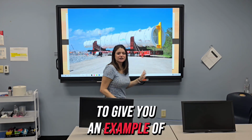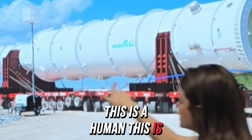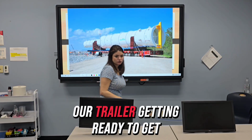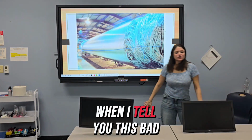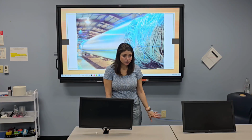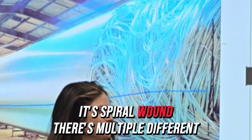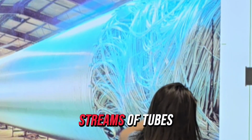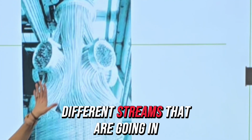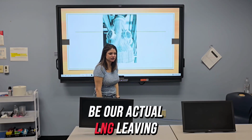To give you an example of how big this thing is, this is a human. This is our main cryogenic heat exchanger on our trailer getting ready to get installed. When I tell you this bad boy is a tube cluster, it is a tube cluster. It's spiral wound. There's multiple different streams of tubes. So you can see here all the different streams that are going in and out. The very tip top is going to be our actual LNG leaving.